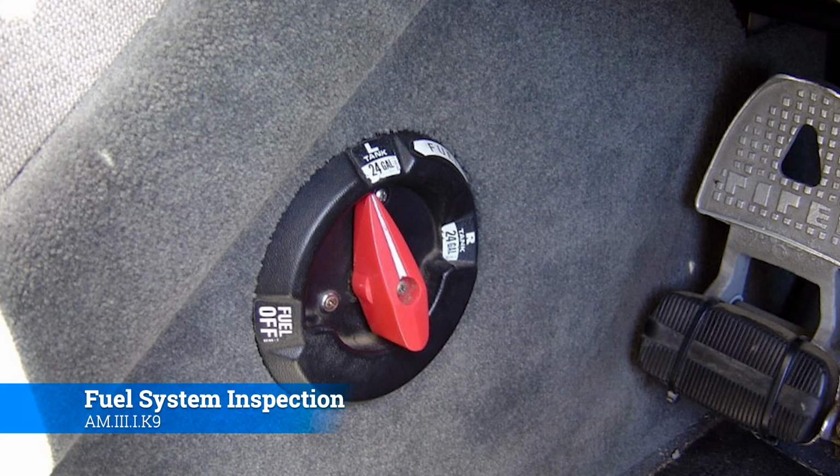Now, fuel selector valves, you're going to make sure that they operate properly, that the fuel actually can pass through them, and that they don't have any sort of leaking around them. That's going to be the main things. Now, valves are going to be very different. This is off of, I believe, a Cessna 172. This one I know is a Piper Cherokee.